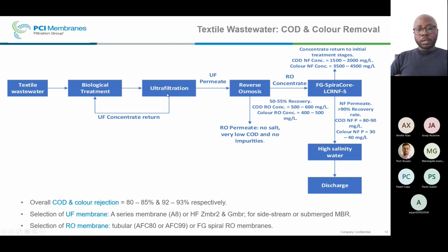treatment process. Of course, there are other technologies available that could be used for the textile wastewater. This could be looking at dissolved air flotation, or looking at the use of ozone or ultraviolet for the treatment of this wastewater. But from our side, with regards to the work to be done from PCI, the incorporation of biological treatments together with ultrafiltration, as I've explained before, we have a number of membranes that could be chosen from.